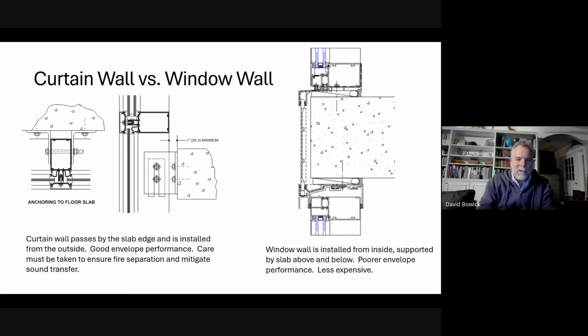So we had been talking about curtain wall. This is window wall. So remember, L over 23 was our rule of thumb for a curtain wall. Window wall is about 25% less than curtain wall, which would suggest that window wall can span about 75% of that, maybe L over 18, something in that range.